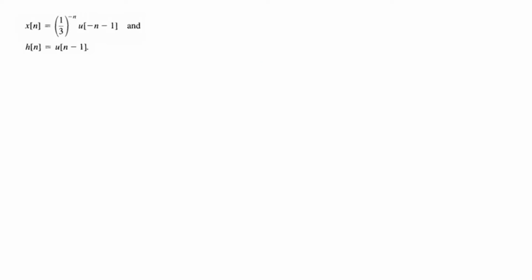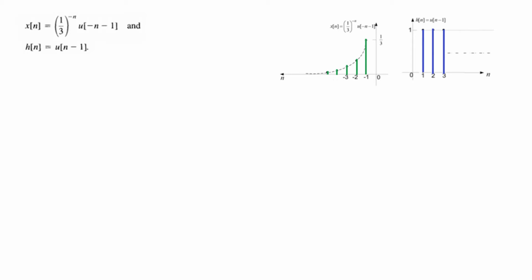Okay. And now we go to the actual solving, and I'll strongly recommend that if you have not seen my previous videos on this topic, then you must see those videos, because a couple of things I'm assuming here that you already have learned. So this was our x[n], and this is h[n]. And we have learned from the formula that x[n] convolution h[n] can be written in this form: summation x[k] multiplied by h[n-k]. Now how do we get these two terms?